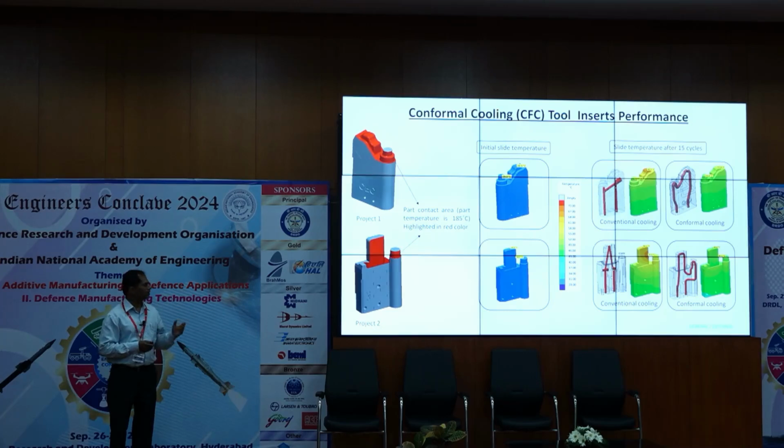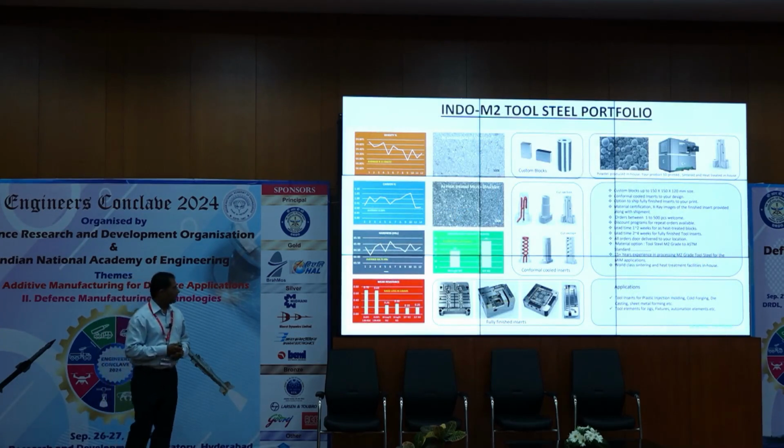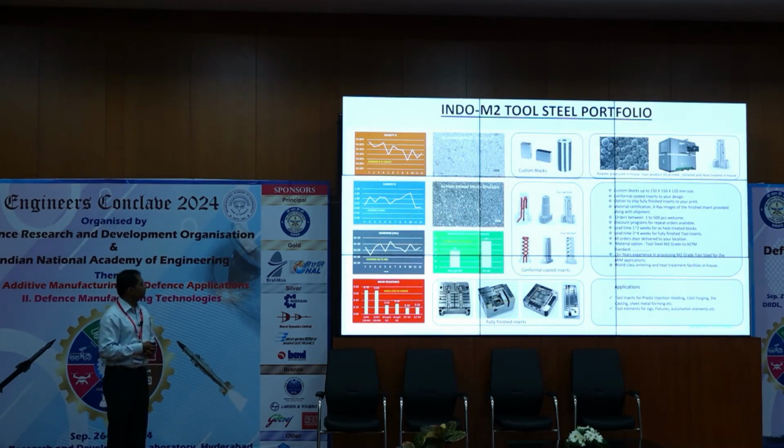And why conformal cooling applications? Cooled tool inserts are very much required for different processes like injection molding or die casting, because of uniform mold temperatures, through which you can avoid a lot of defects in the components. You can get less distortion, fewer defects, and good emission control. So you can adopt additive manufacturing and the material combination to get better processes and better components. So it's all integration. Again, you are using the new processes and the new materials for enhancing the existing processes and the components.